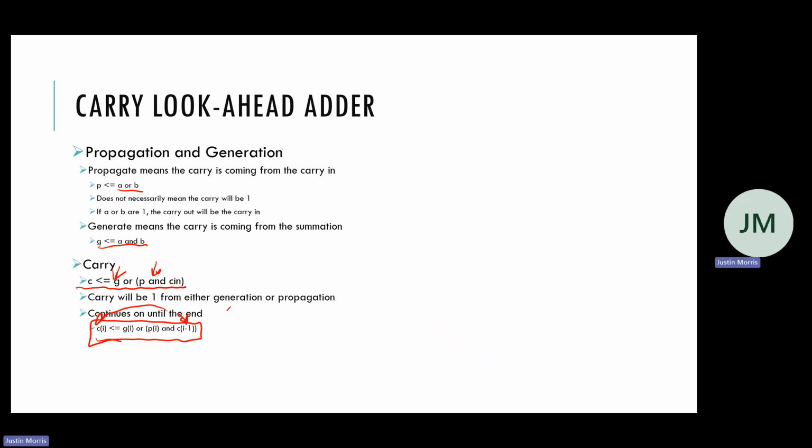So you only need to expand it up to 4 bits because you're just making a 4-bit carry look ahead adder. You can model this in data flow if you want. That's what I would suggest because you have the equation here. You just need to expand it out. Make sense?